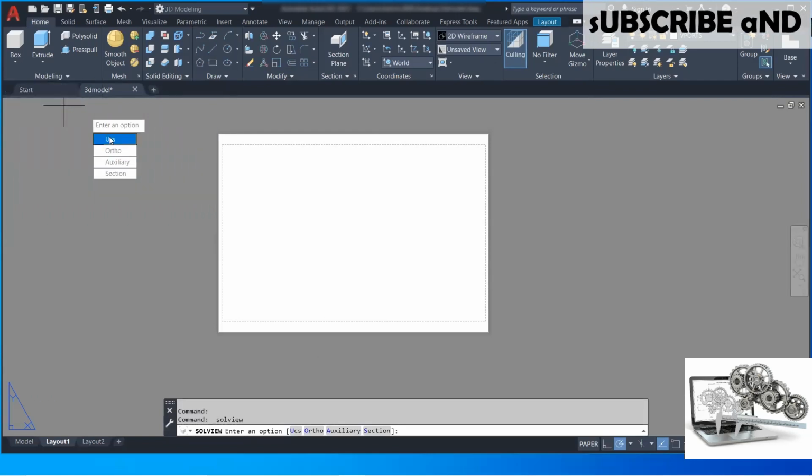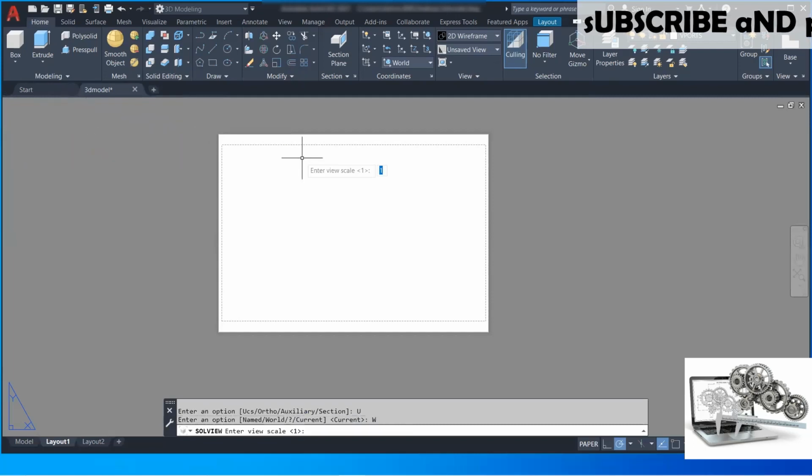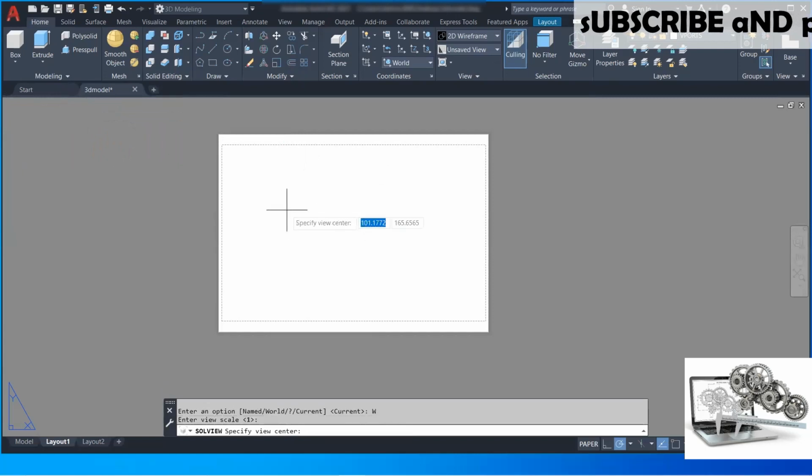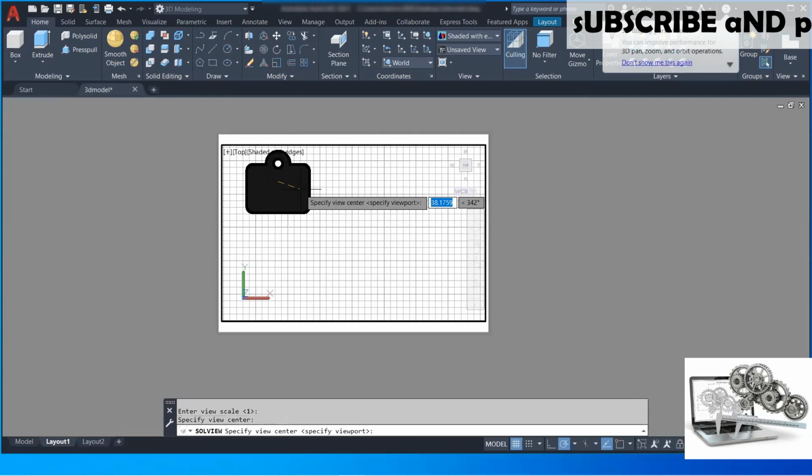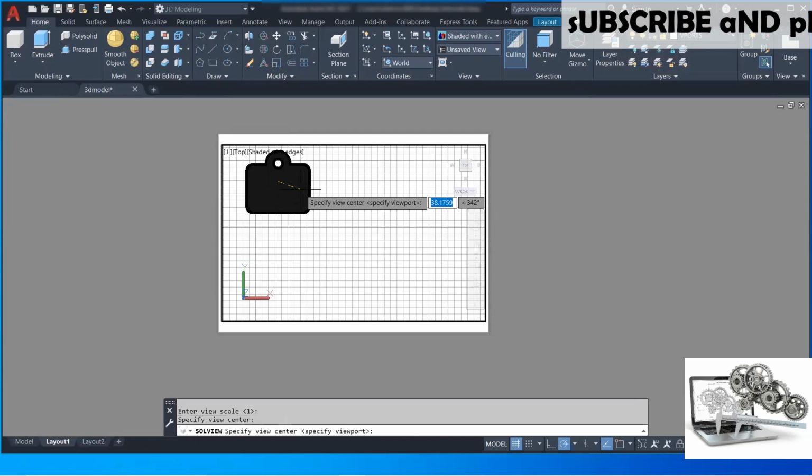Now let's start with the solid view command. Here you will get different types of options. Ortho, UCS. You have to select UCS. After that you have to select World, and then you have to give a view center. The first view is created. So again it is asking for a view center. Press the enter key here.